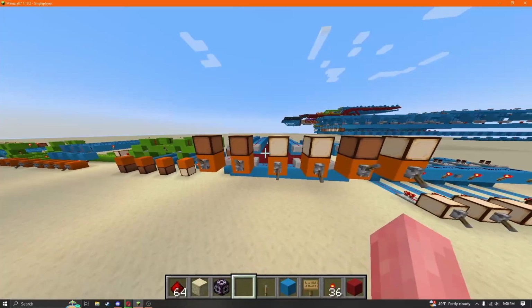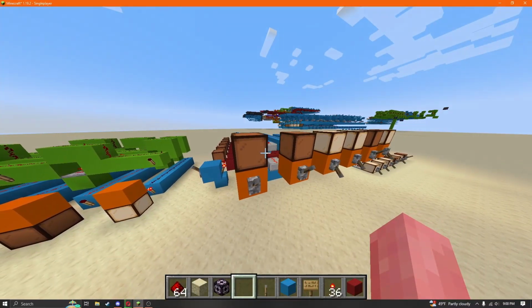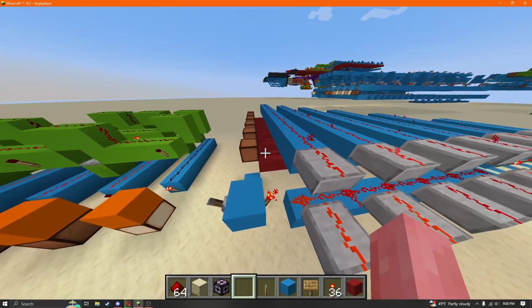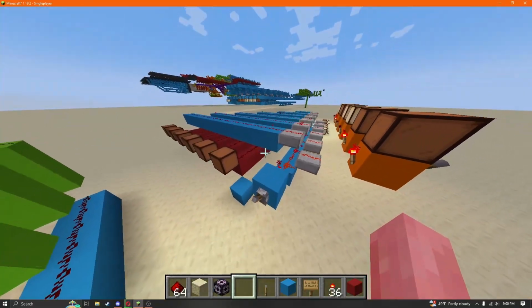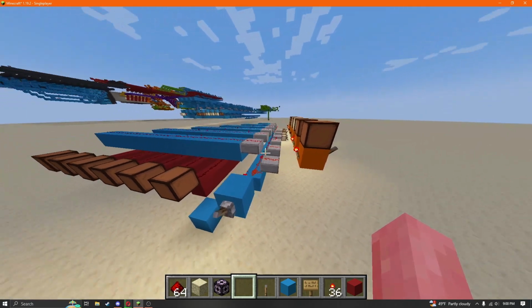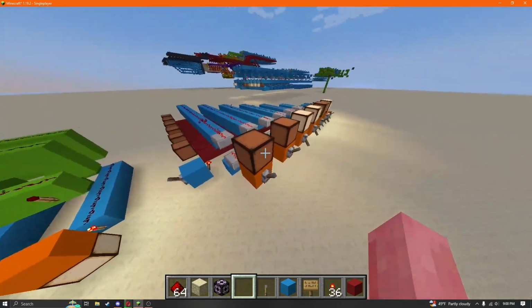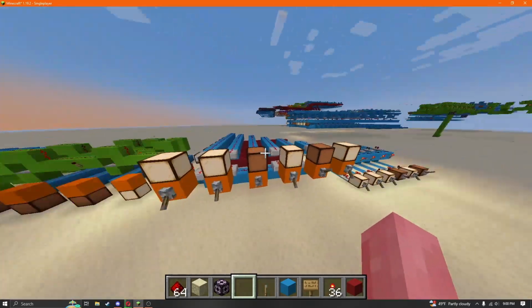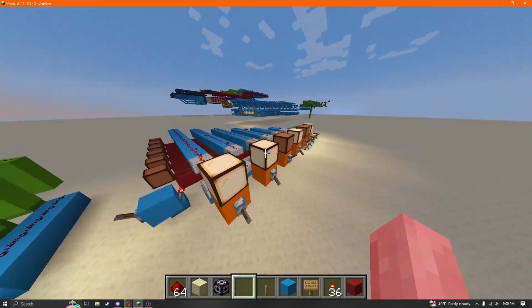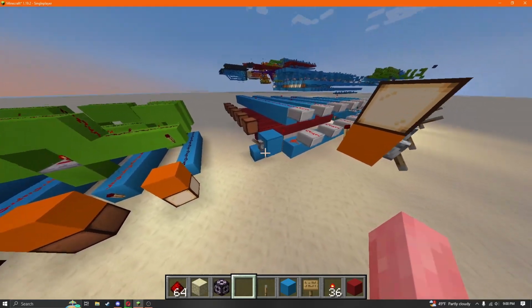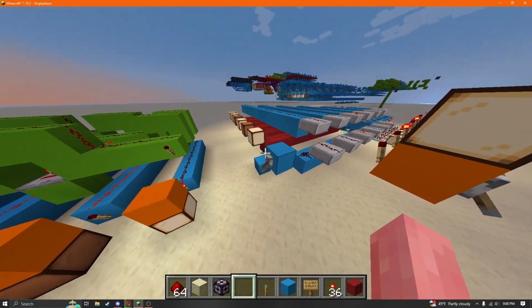Similarly, if we're going to be building a calculator, we need to have control over where information goes. So the red here is the bus. It's a system component that runs throughout the length of basically the entire computer, and it needs to be very specific in what values it accepts onto it and which values it doesn't. So right here, the bus is actually disabled. Let's say this is like a register or some user input, and we need to write it to the bus so that some other component can read it. We have to enable the output for this bus.